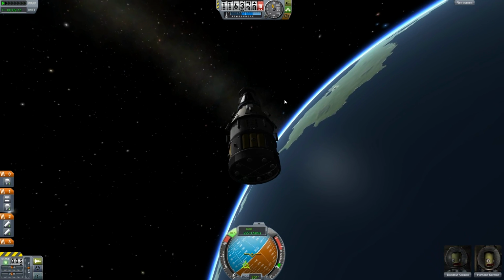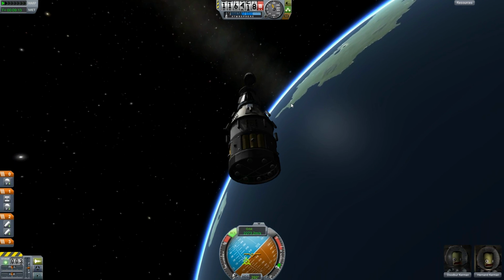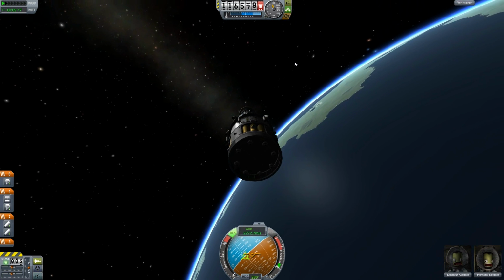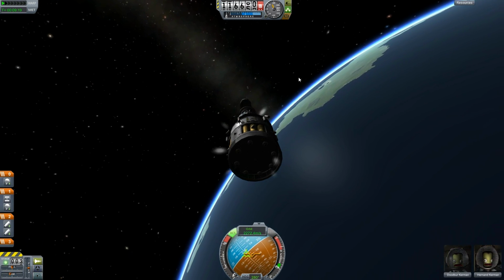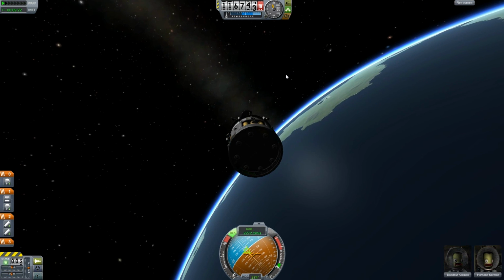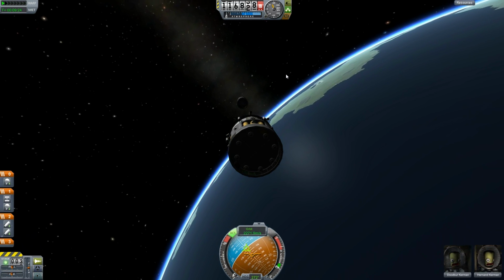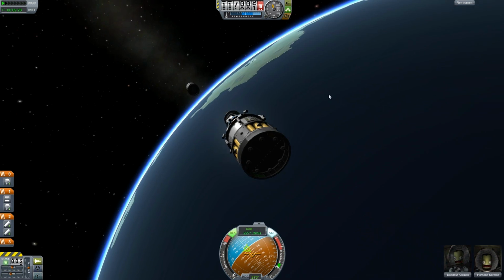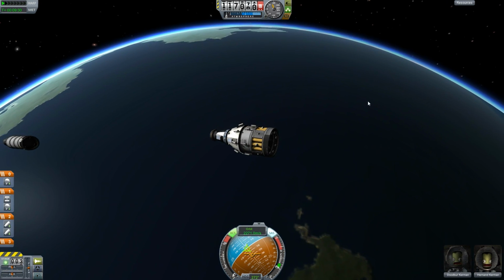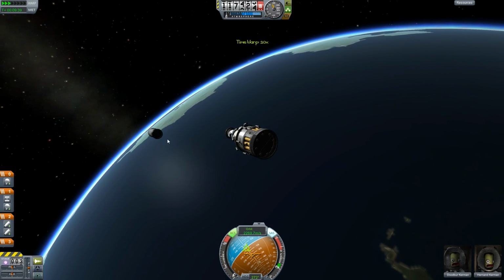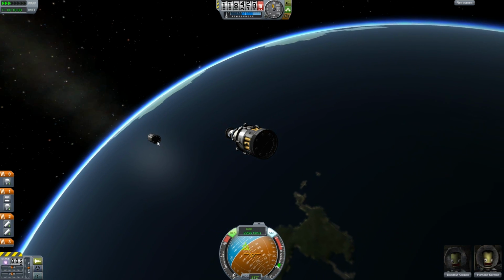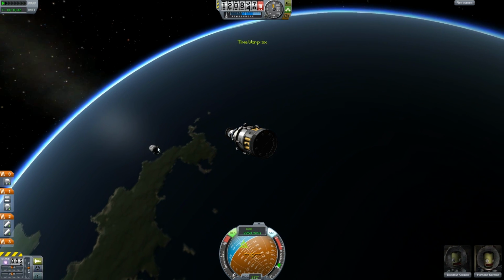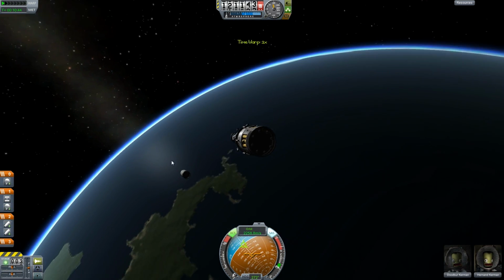And part of the other problem was that nobody really knew how rendezvous physics worked. So what would happen is that they would accelerate towards the target, which was the second stage of the launch vehicle, and they would end up going above it, because as you're going faster, that increases the altitude of your orbit, and that's not very intuitive, and it's not anything that they'd really trained for either.